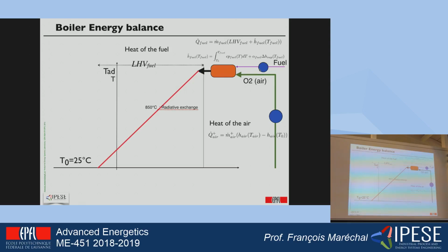So it's possible that it will come with a certain amount of energy or without a certain amount of energy. For example, if I'm receiving the natural gas at 25 degrees C or at 0 degrees C, I will also have to take part of the energy supplied at the level of the combustion to preheat the fuel that is entering. Okay? The same for the air, which is not going to enter at 25 degrees C, but perhaps at -6. In this case, I will also have to preheat the air inside the system. But when I do the combustion, I will obtain the adiabatic temperature of combustion.